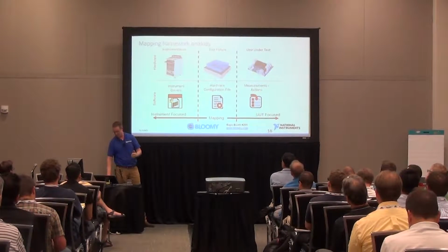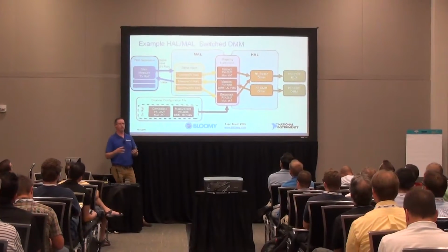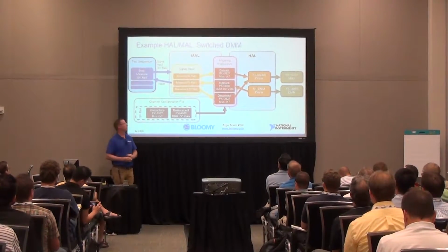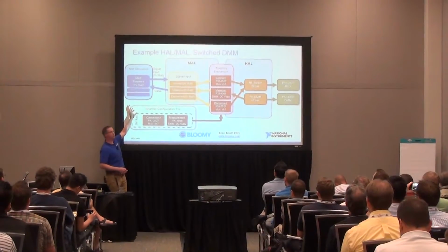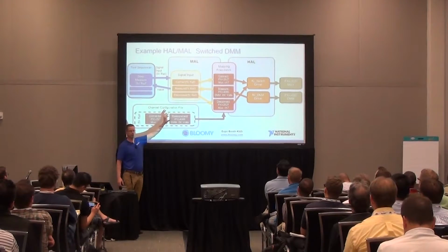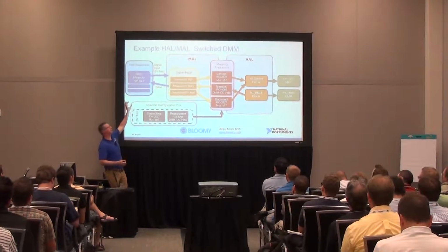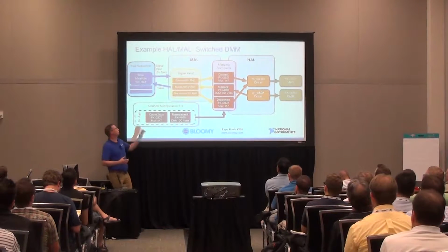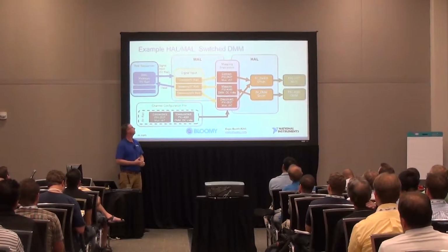Good. So let's take that same example we did before of the switch and DMM and break it out for an abstraction framework. So at the top level, you still want to take your measurement. In this case, though, we're going to call our measurement abstraction layer. And here, we're using our signal input. And so we're going to say, I want to take a signal input, and it's using an alias called 5-volt rail. So we call our signal input type, or this is our step type in TestStand.